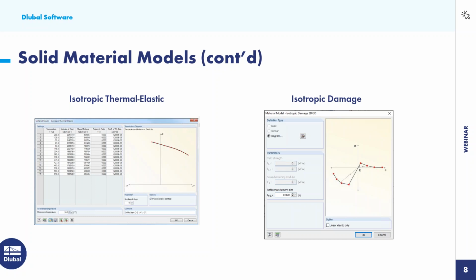for example. And then finally, we have isotropic damage, and this might be used for steel fiber reinforced concrete where a continuous reduction of strength will occur due to cracking. This utilizes Mazar's damage model, and an isotropic stiffness is reduced with a scalar damage parameter.